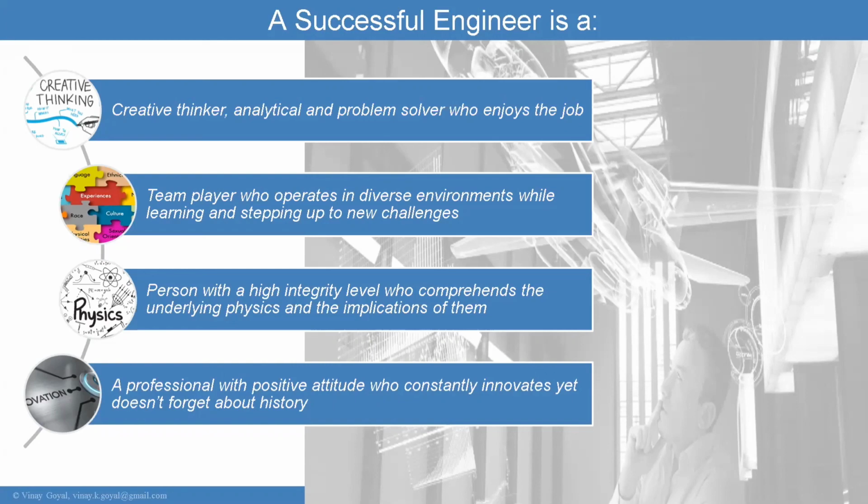And we have done a lot of simulation, short circuit simulation, which is a multi-physics type of situation where you have a combination of structural effects with thermal effects. It's a dynamic type of event, so that adds complexity to the model. It's a thermal type of simulation as well, just to check how far or how close we are to the limits, in this case posed by Underwriters Laboratories, which is the certification agency, and that has given us confidence. We were very successful passing the physical tests at the first trial. So a success story of the importance of calculation and simulation.